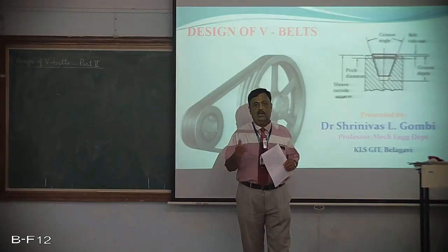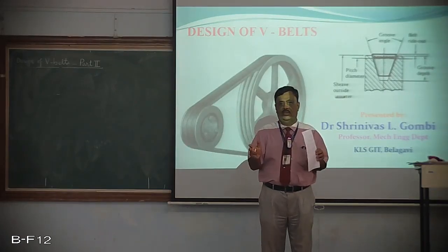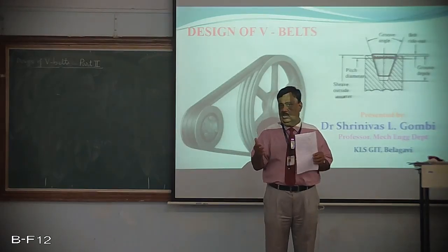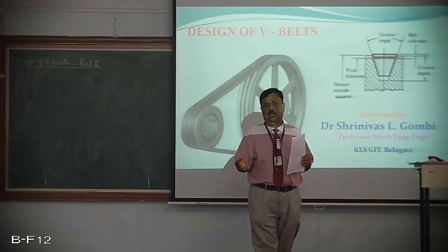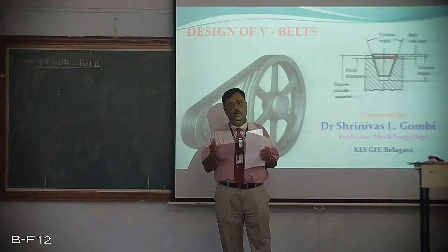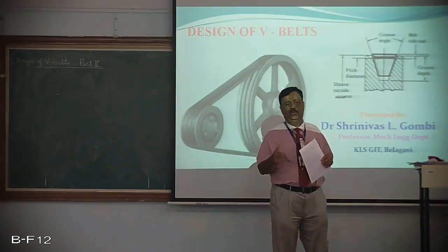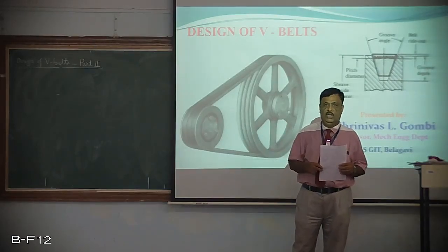So depending upon your requirement, space size available, pulley size and weight to be put on the shafts, considering all these you can make your choice. Of course, the economics also matters, because as the belt selection goes from A to B, they are more expensive. Depending on that, you can purchase the required type of V belts and utilize them in your applications.